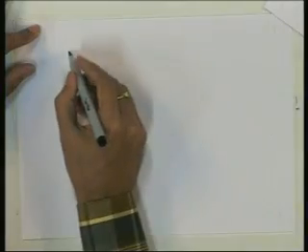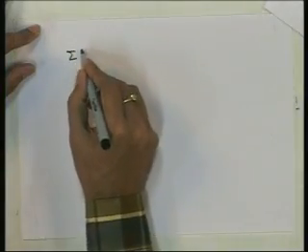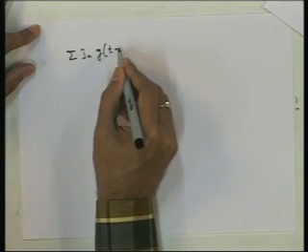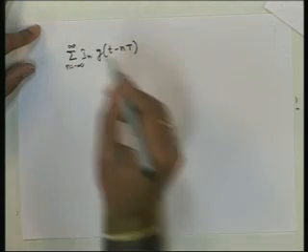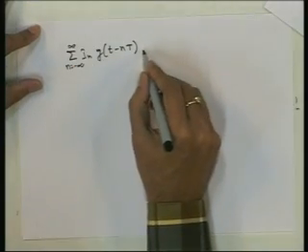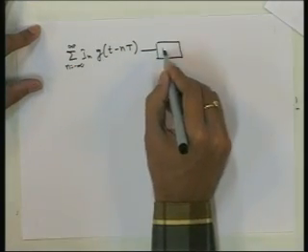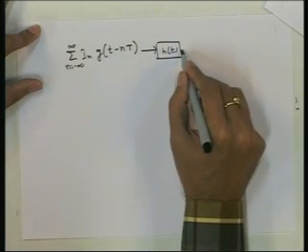Okay. So, let us first formulate what will happen if we do not have ISI free transmission. What is the exact form of ISI at the receiver? If we transmit summation I n g t minus n t, n equal to minus infinity to infinity, if this is transmitted through H t, then it goes through R t.